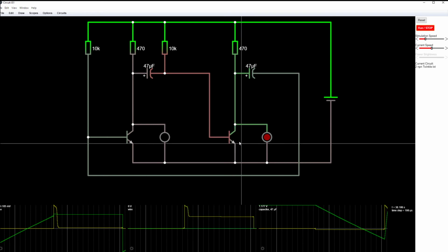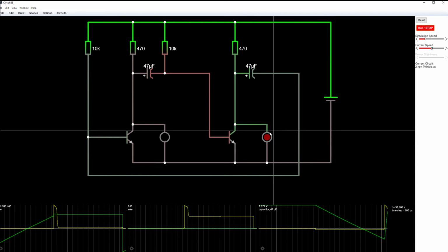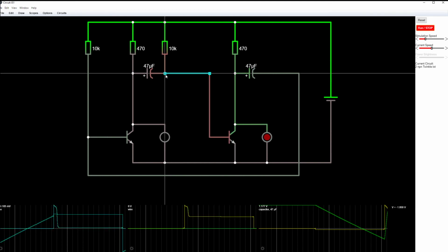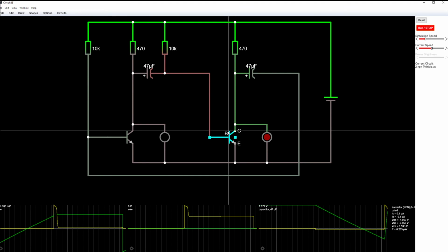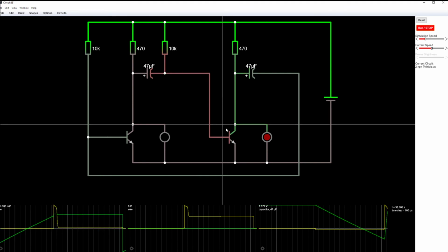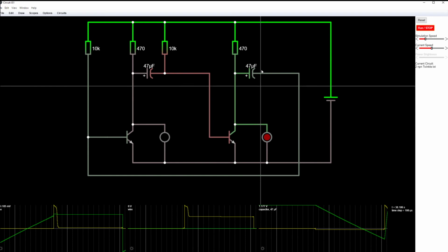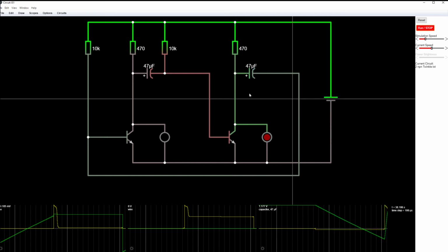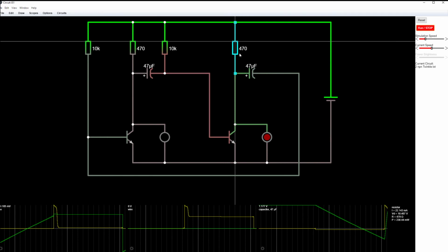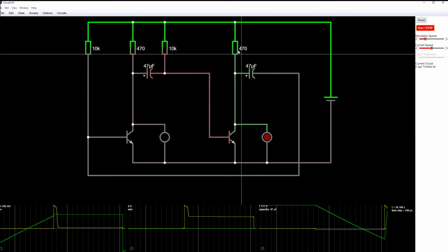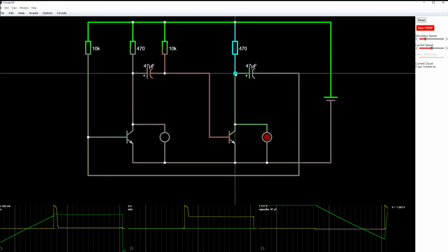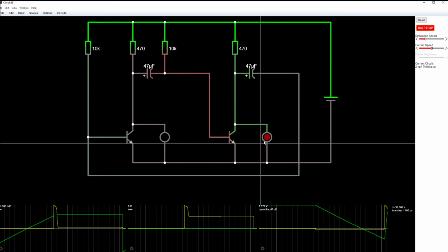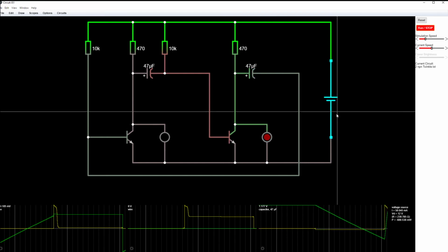So what happened here is we had our system, so this LED light acts as some sort of a resistance, because it has more resistance than the transistor. As soon as this transistor is turned off, which we know this one's turned off because it's got the negative function, we already know that. As soon as it's turned off, this capacitor is now not directly connected to the power supply. The capacitor is in between the resistor and the LED light. So this over here is not connected directly to 0. It is something in the middle. So it is a value that is higher than the 0 at this point.